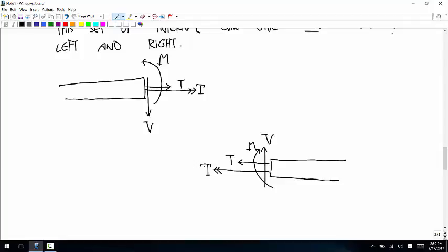Okay, so the idea is you call tension a force going this way on a right end of a piece you're isolating, and a force going the other way on the left end of a piece you're isolating. And if you use that sign convention, now there is a consistent answer for what's the internal load at a point. Calculating it isolating the left half and calculating using the right half would give you the same values. And so that indeterminacy is gone.